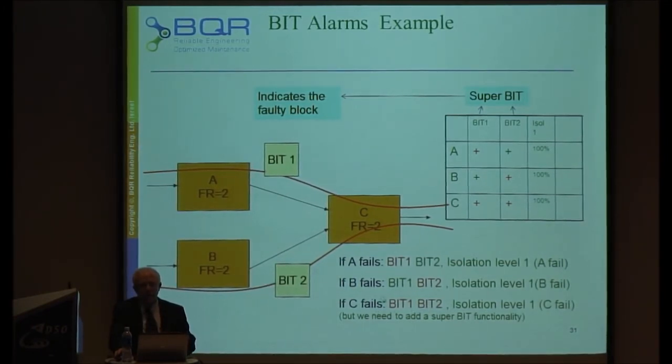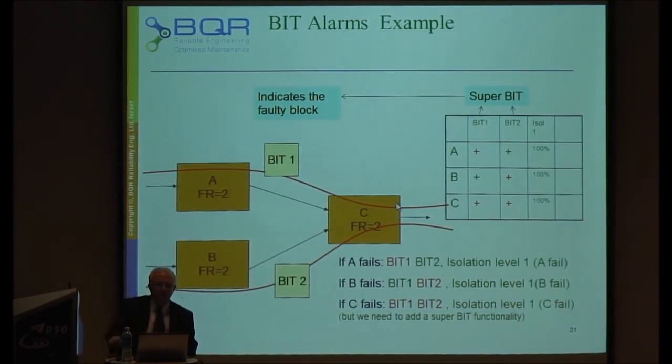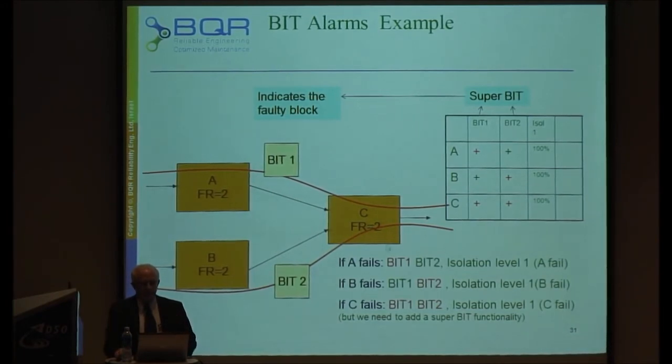So I need to improve my model of the testability. What I have seen mostly from engineers is that every bit can detect all assemblies. This means that I can never isolate to the source failure. So the ideal is that every test tests only one assembly, not 2. So if I have 3 tests that test A, B, and C separately, that is the best. I don't need to make any decision because I know exactly which one failed. So this is the built-in test analysis.